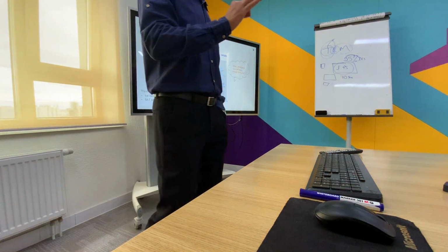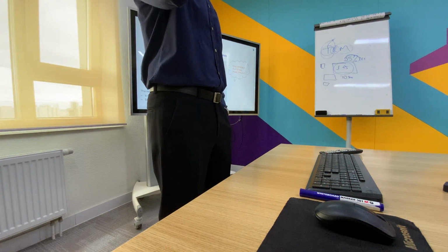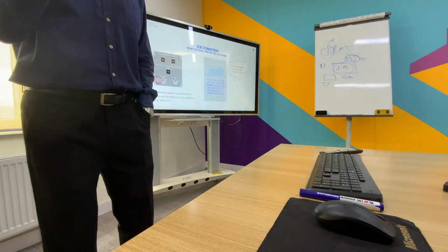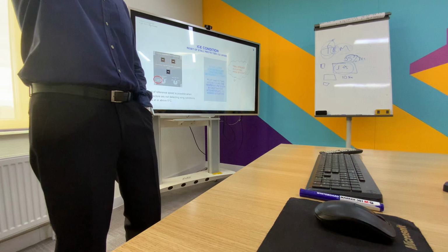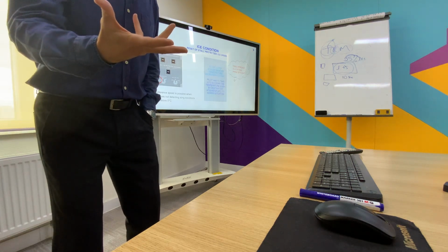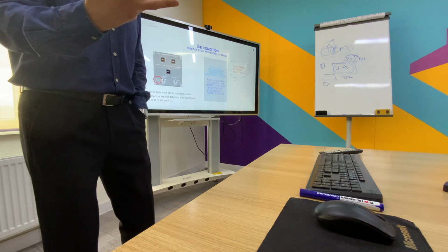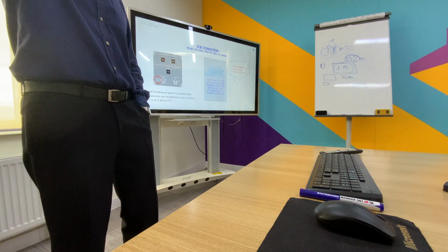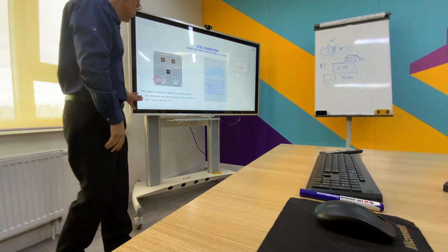If I'm seeing an icing condition there along with it, I cannot reset, because if I see an icing condition, it's an icing condition. Okay? There's no way to reset it. But if I have only the stall protection ice speed, I can reset, as long as I have this situation.